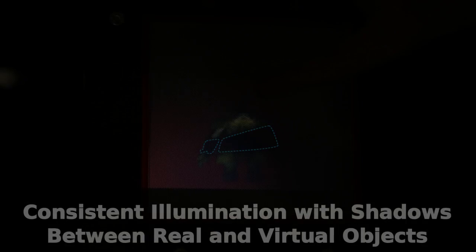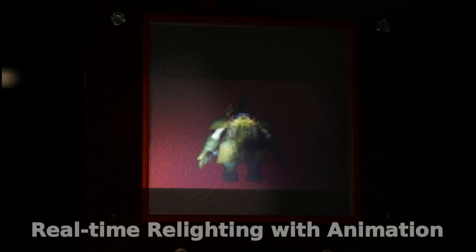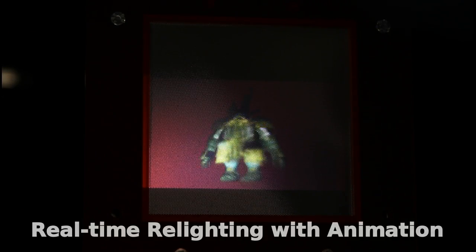Our real-time GPU pipeline enables our 8D display to dynamically relight moving and animated models. The pipeline deinterlaces images captured from the back of the lens sheet to synthesize a 5x5 input light field, and then synthesizes a 5x5 output light field by projecting every view of the input light field onto a 3D scene and capturing the output from each output view direction. Finally, the output light field is re-interlaced for display through the lens array. Here, the interlaced views are visible.